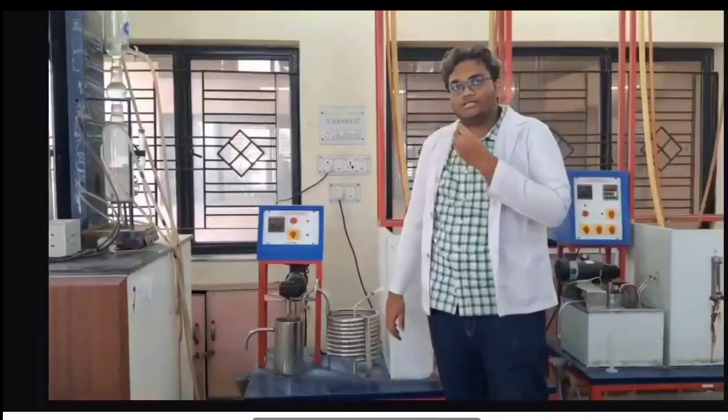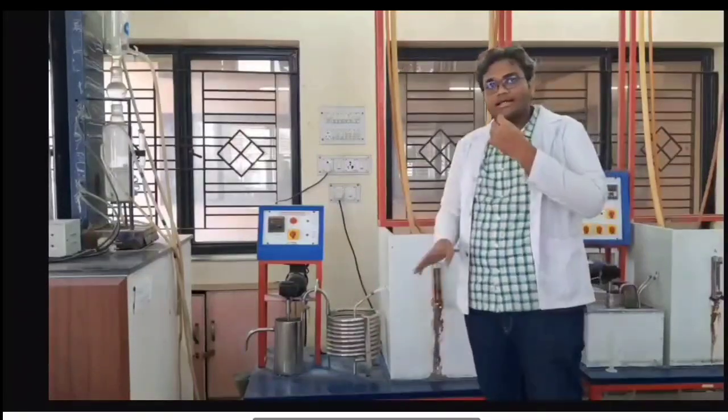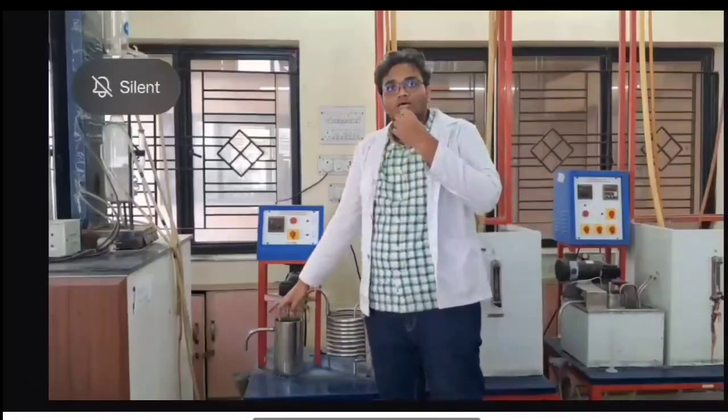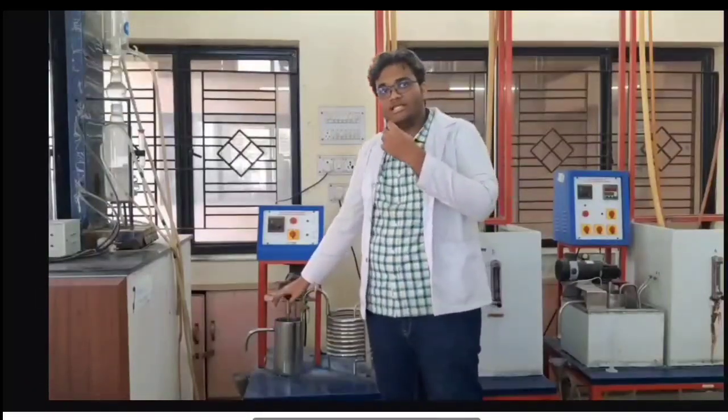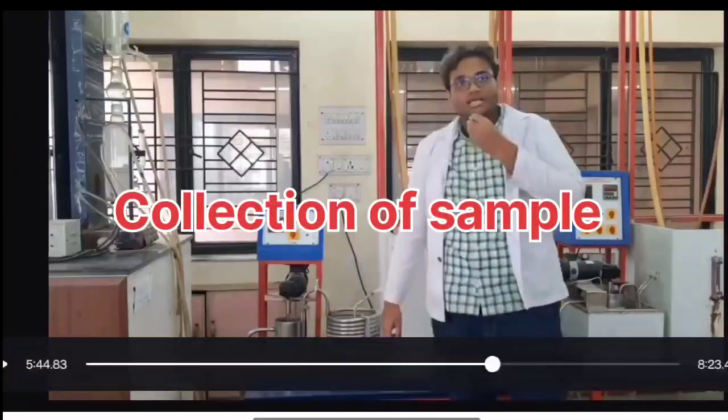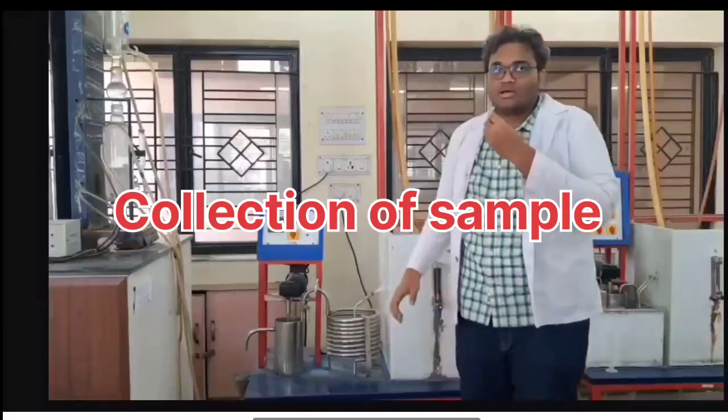Going into details of the explanation, first, collecting the sample. We'll start by collecting 20 ml from the CSTR, which has achieved steady state condition, into a clean conical flask.